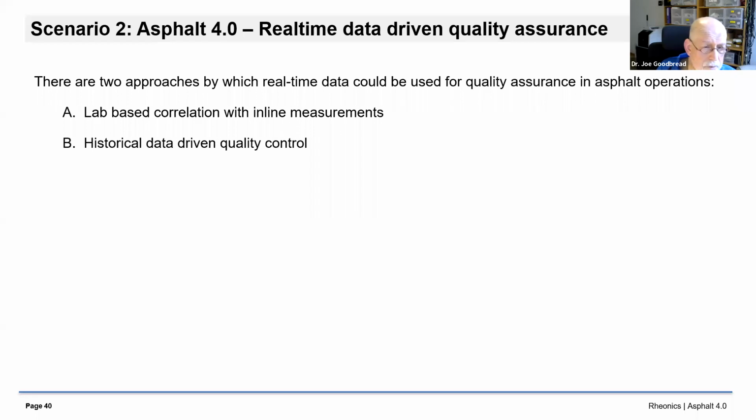It is unlikely, for instance, that a Saybolt cup viscometer will give the same viscosity values as a vibrational or even a capillary instrument, even at the same temperature. But the availability of continual data streams allows correlation of the inline measurement at the moment of sampling with the lab report on that sample. This allows building a model in which the equivalent laboratory value can be calculated from the inline data.